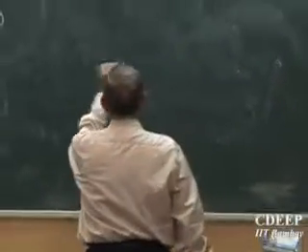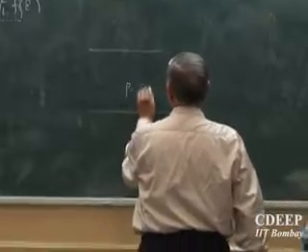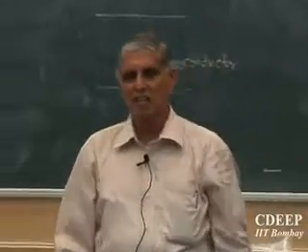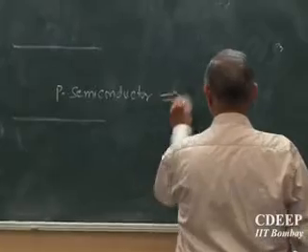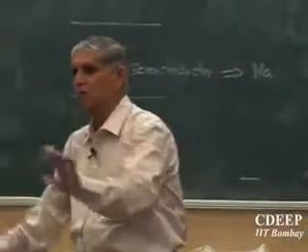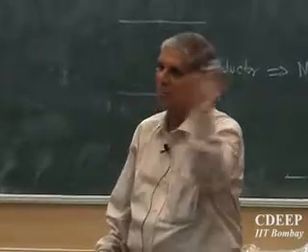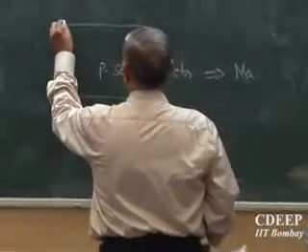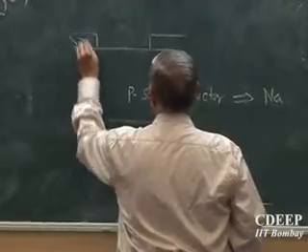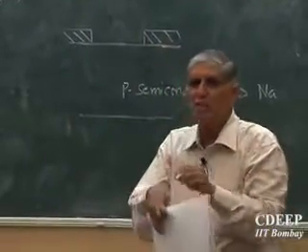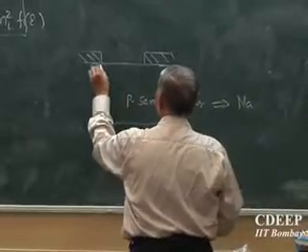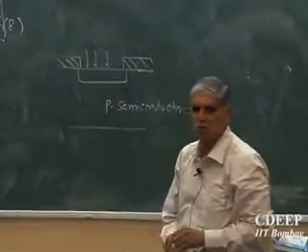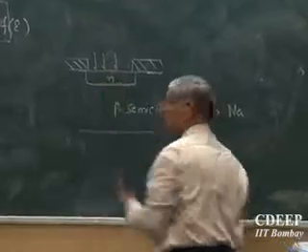Please. I start with a semiconductor, let's say N-type or P-type. I have a uniform acceptor density of NA. Let us say at room temperature, all of them are ionized. So as many NAs as I give, that many holes are created. And then by technology, by some process, I create what I call a barrier layer of silicon dioxide, create a window in that where silicon is exposed, and inside this I put N-type impurities and give heating to this for driving, to push the impurities in, and this becomes N.